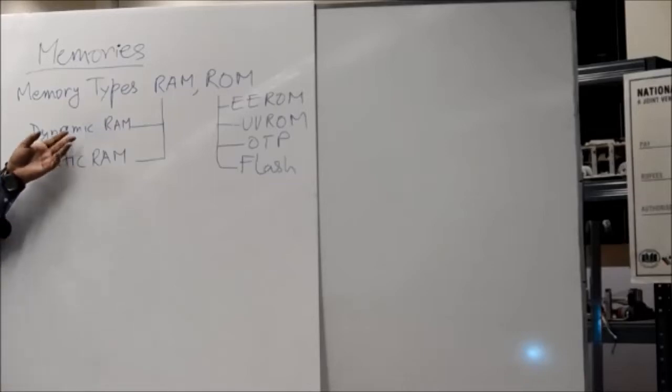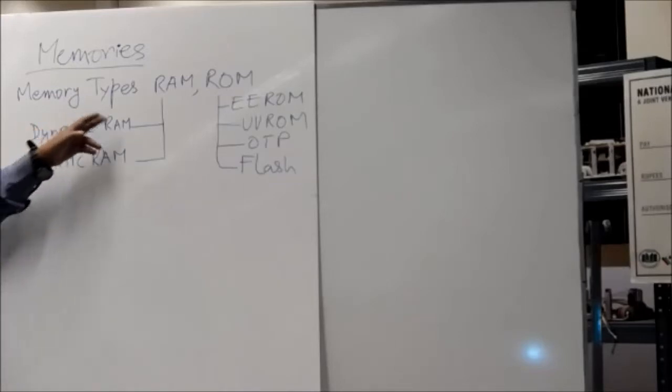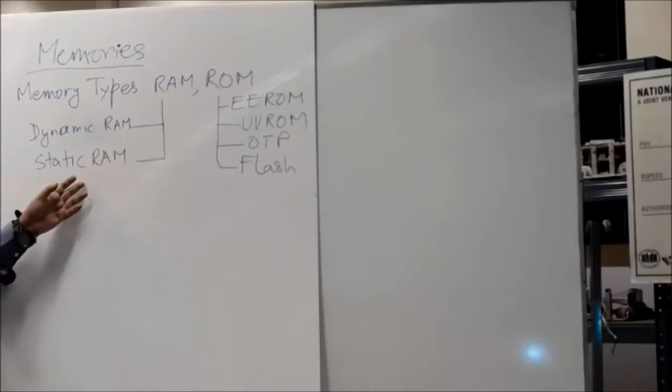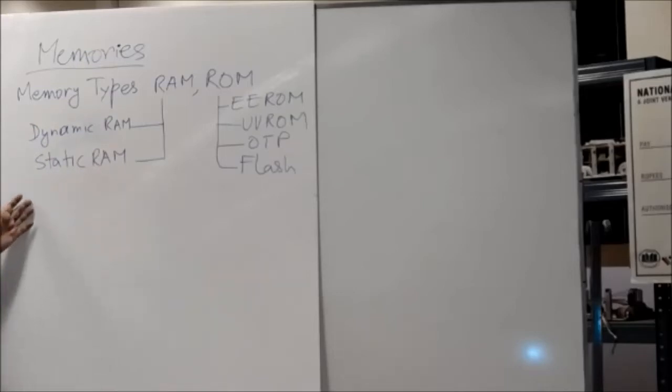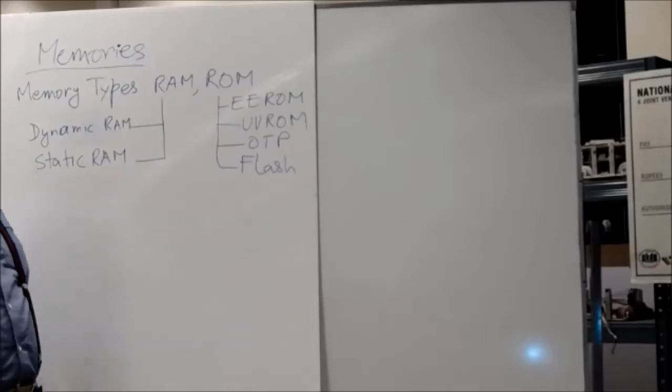So when the RAM is not being used by the computer, there is refresh hardware that takes over the RAM, and it reads the data from a particular location, and rewrites it on the same location. So by rewriting the data on the same location, it basically refreshes all the capacitors again. So that way, you have a dynamic RAM to store different types of data.